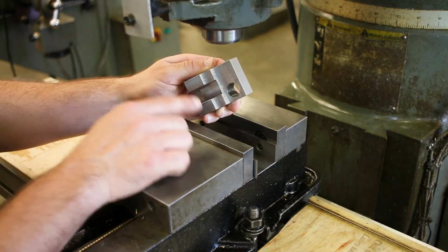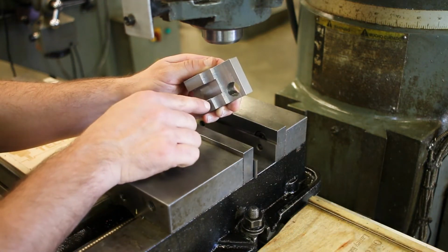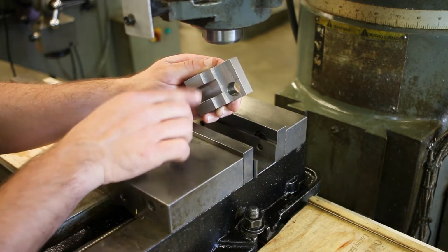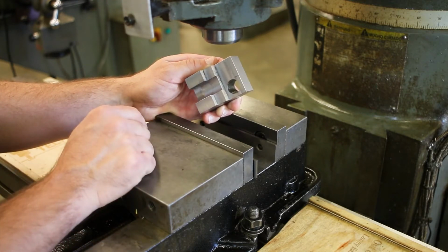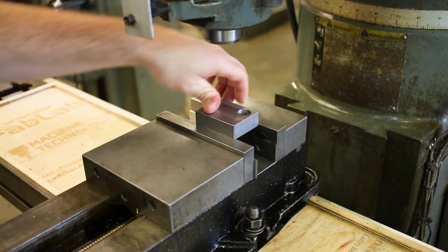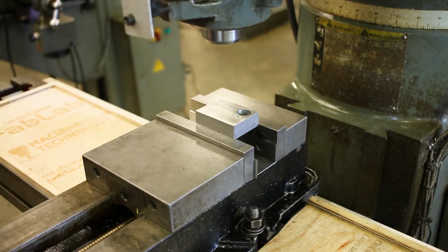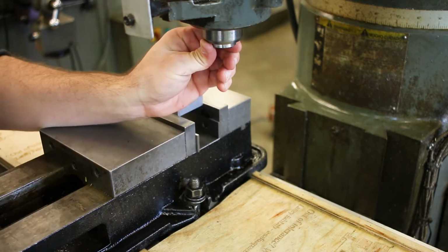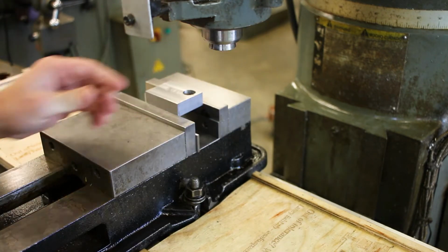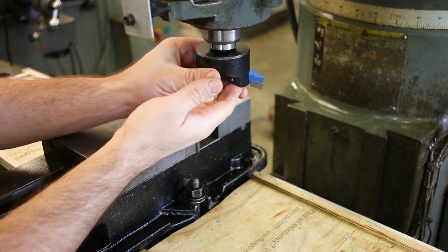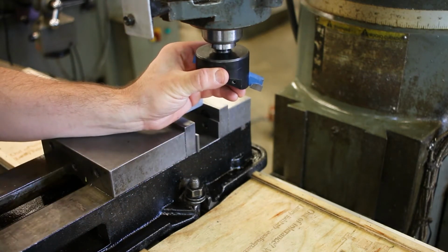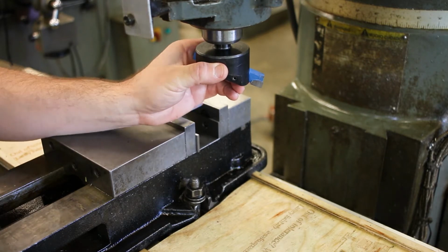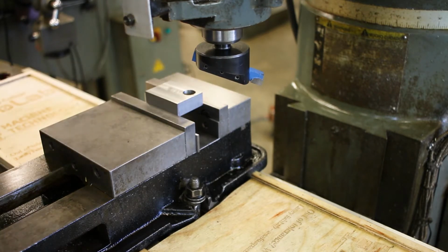By the way, if you haven't done so already, make sure that you deburr all of the edges on the top of the part that you made with the roughing end mill, okay? That's really going to affect the way that this sits down on the parallels. Okay, tighten that down. Okay, collet goes in. Get that started. Followed closely by the fly cutter. Pull the drawbar in. Lock that down.